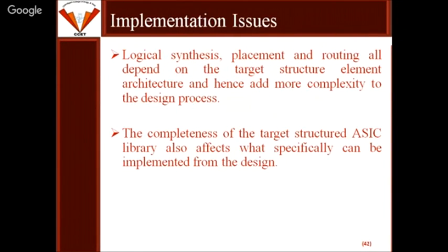Implementation issues are that logic synthesis, placement and routing all depend on the target structure element and architecture, and hence add more complexity to the design process. The completeness of the target structured ASIC library also affects what specifically can be implemented from the design.